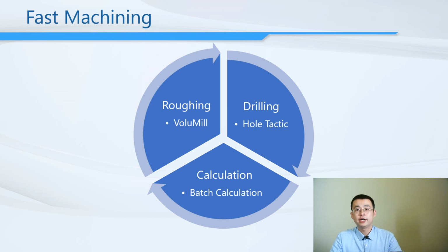And for hole drilling jobs, we have a hole tactic to drill all the holes in the part with one click. It will automatically detect the hole features, including the diameter, the hole types, and the counterbore or countersink if it has. And it will automatically select the tool from the library and create the operations by the rules.